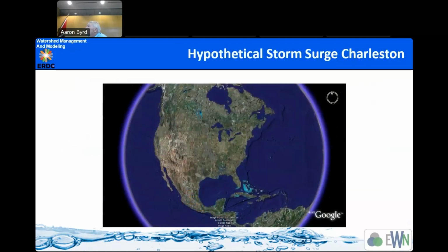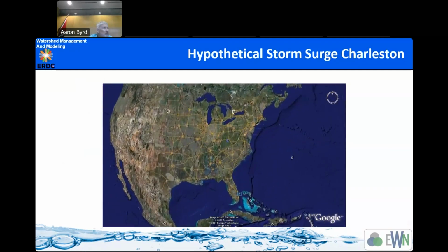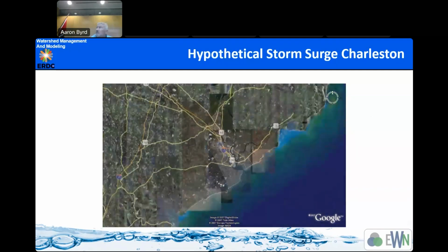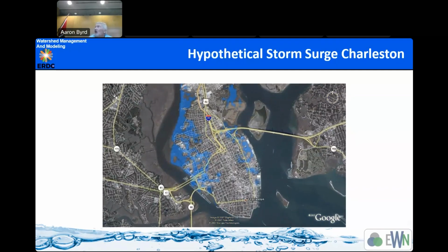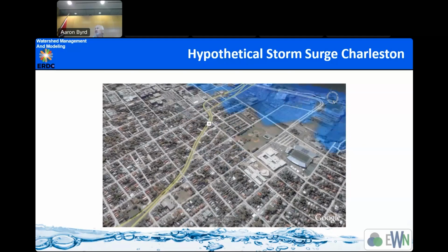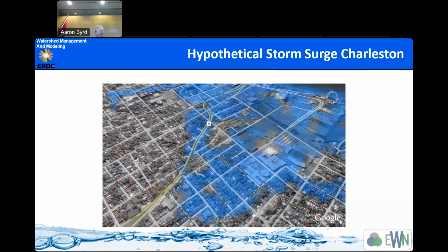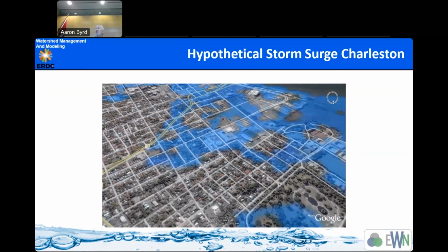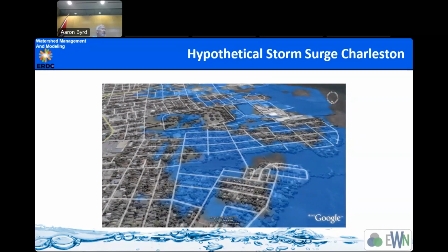So, I think this is our last slide. How do you make this thing? Is it safe to say most of our models lately have been running 10, 20-second time steps? Is that a good starting point, you think, Chuck, still? I mean, it's a place to start, I guess. But I always want to run time and space convergence studies, always, 100% of the time, because you can save so much time down the road if you do it in the beginning. You optimize your model for accuracy and efficiency up front.